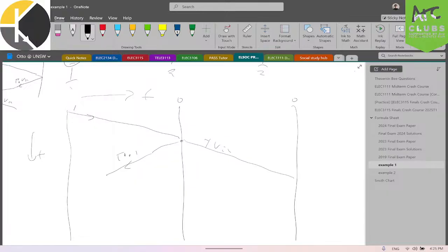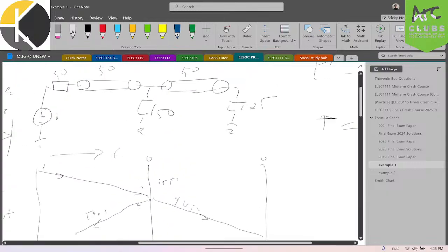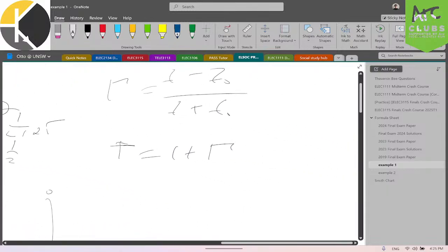The voltage that the next line will see on its input is just going to be the sum of the incident and reflected voltage. So the voltage that the next transmission line sees on its input is the sum of those two waves. It's going to be 1 plus gamma. This is going to be sent this way. It's just an easy way to understand why this is the case. And this is also possible to derive using the incident and reflected powers.